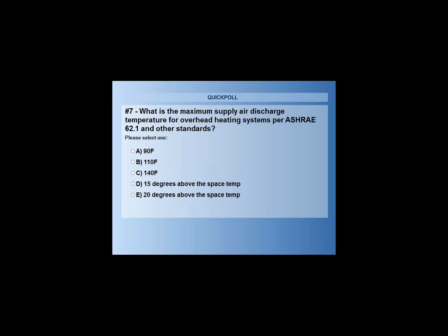Eli made a comment that you can use hot water coils to be supplemental to the heat pump systems. That is true. If you have heat pump systems that are not designed to carry the full load, which is very common because the heat pump also has to do the air conditioning work, and typically the air conditioning BTU requirement in many cases is lower than the heat pump BTU requirement on a very cold day. So we size it for the air conditioning mode, which means the heat pump can't do it all by itself when it's 0 or minus 10 out, or even positive 10.